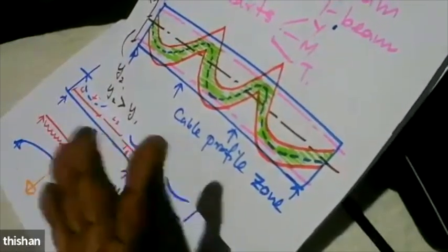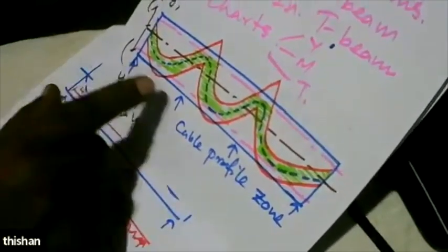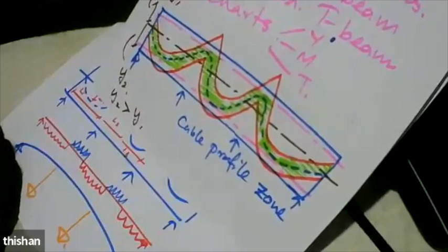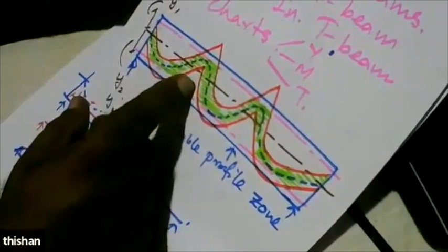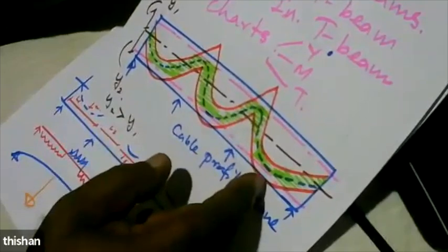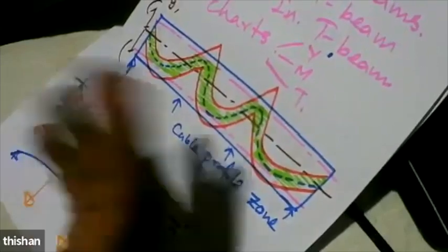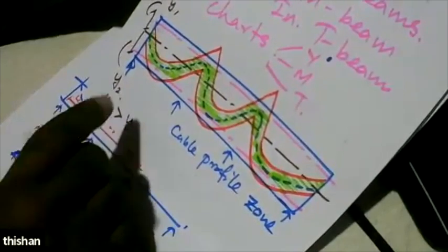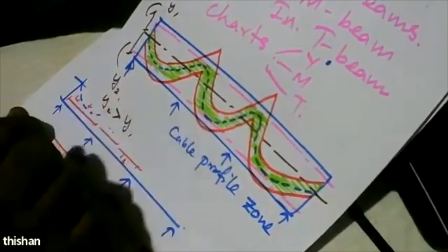Because before doing that, you have to draw the moment diagrams at each critical section, that is here, and then see which prestress will work. And sometimes here you will find the prestress has to be 18,000. Here you might say 20,000. Here 22,000, and then here again 18,000. This 17,000. Then you will say, okay, I'm going to select 22,000, because we always know the minimum will not work, but a higher value can always. So out of all these, the highest is 22,000. Then we might select 22,000.